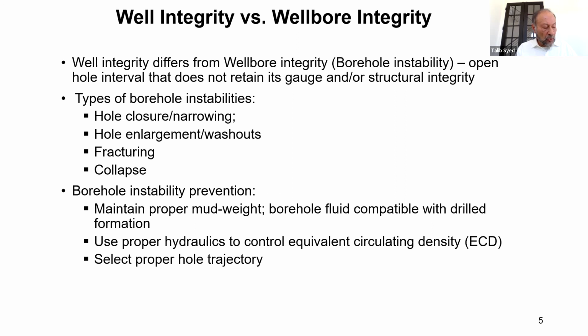Shales are the ones that cause most wellbore instability, and more than 75% of all formations drilled are shales. So shale instability can be due to mechanical reasons or chemical, resulting from the shale-fluid interaction. So it's important to prevent shale hydration and dispersion. And that's the reason why we use oil-based muds and synthetic-based muds instead of water-based muds.